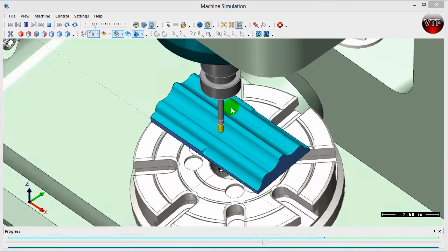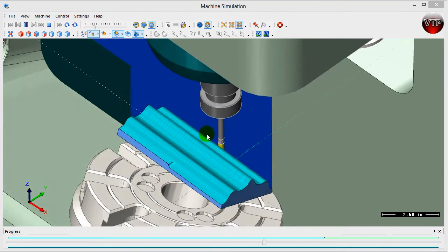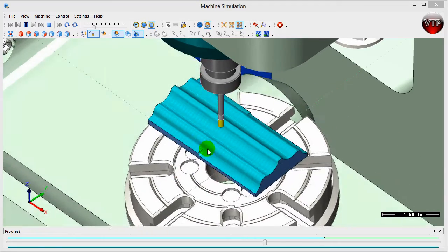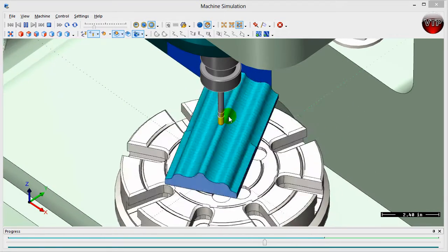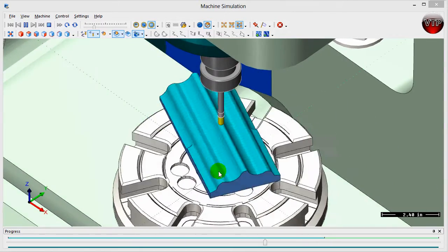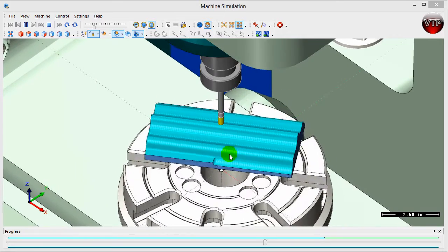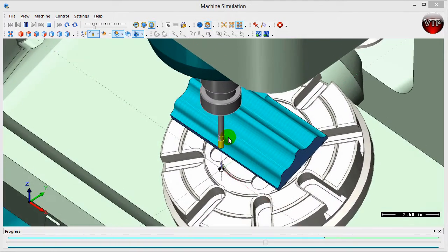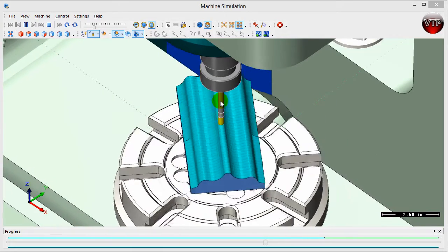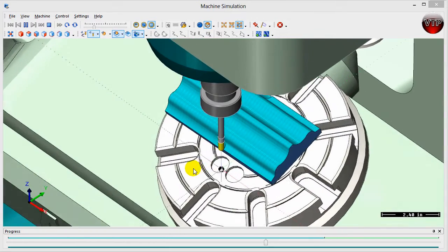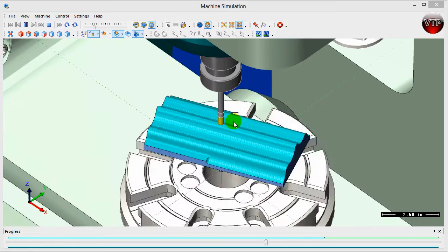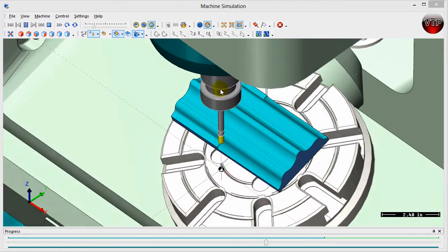That's mainly because we assigned it a line to be guided through the entire time, so the tool is exactly vertical on the part the entire time. You want to be careful when you machine things like that, because as you can see, while the part is moving, the tool can have a tendency to hit other parts of the part, and that's where you have to make sure you have your options set up correctly so you don't have any tool collisions with your part while it's machining. And that's one of the reasons why I did not place the tool to stay down the entire time in this process, because I want to make sure that it does not machine any surface of my part while it's doing the operations that were given to it.